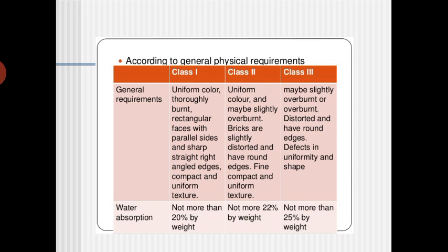which many brick industries are facing nowadays. If the brick has to be sustained for a long time, it has to be completely burnt, because when you completely burn it, most of the organics present in the bricks go. Once organic matter is present in your bricks, degradation will start with the help of biological action, and the bricks will not survive for a long time, or will disintegrate with the biological action.